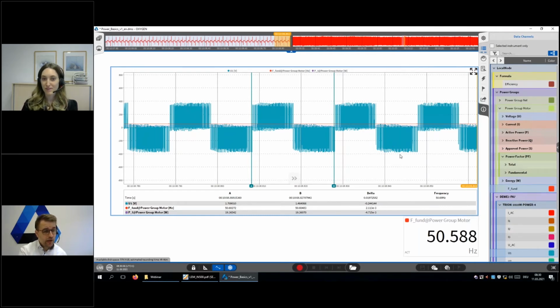So we are doing this for every period, in high dynamic, fast run-ups. This is done automatically. We are going to have always correct electrotechnical power calculations. You don't have to bother, if you have a fast run-up, that your window size may be different and that your frequency is going to be out of this window size and that you don't have a full period in the window size. This is done completely automatically by Oxygen, which is making the work with the power analyzer so much easier.